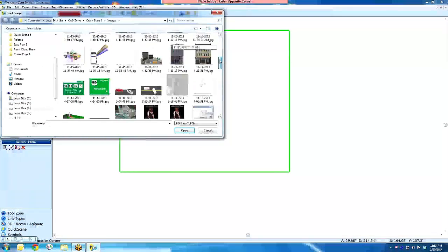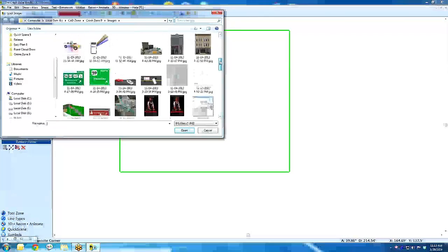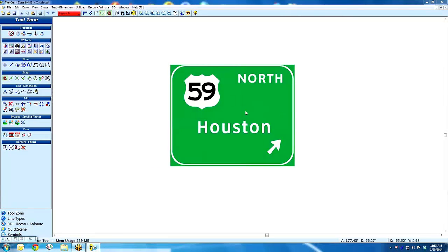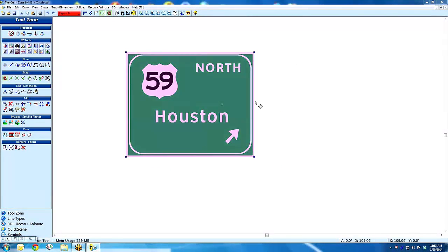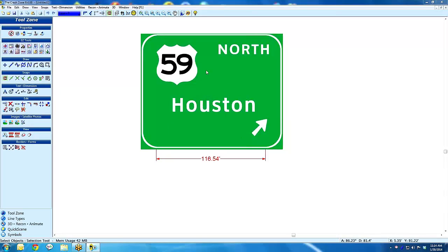And I just don't happen to have a blueprint, but I have some images. You'll get the idea. Here, I'll bring in this. Let's say that's our blueprint. This is just a photo here, like a nice graphic, but there's nothing I can do with it but scale it. So if I knew this was a wall here, that from this endpoint to that endpoint was 20 feet. So I brought this in, it's 116, I eyeballed it when I just brought it in, it's not to scale. Pretend this is your blueprint. I know that this wall here is not 116 feet, but more like 50 feet, okay?